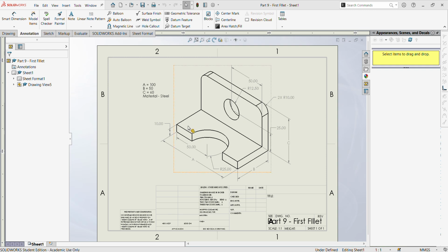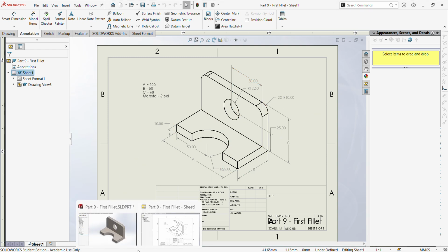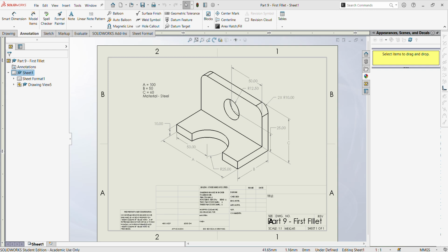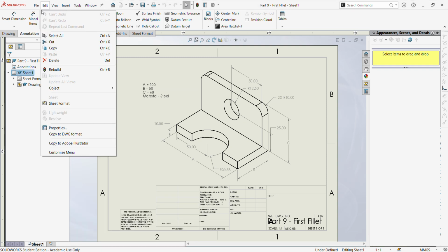First time I made this part, I drew from the top plane, extruded upwards, drew from the top of this, extruded upwards, cut, and then made my fillets. But now, talking to you guys and getting this set up for a redo, I'm thinking that I can do a little better. And I'm going to show you what I mean.